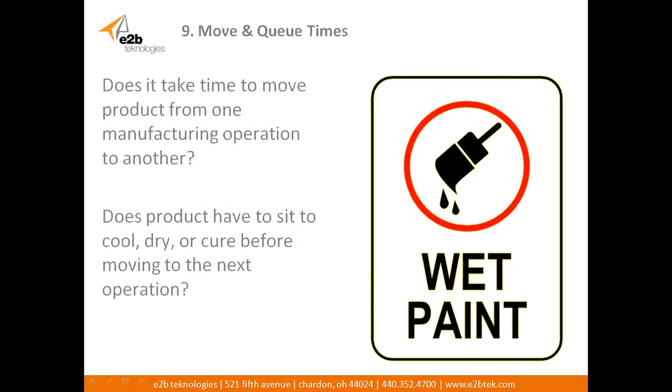Move and queue time. We don't find this in every industry, but it is prevalent in many industries. Move time, pretty self-explanatory. It's the time that it takes me to move my work in process from one machine or work center to another, right? And in many cases, that's in the same facility, so it's not a big deal. But in some cases, I need to actually move that to a subcontractor. Maybe I'm outsourcing heat treating, plating, coating. If I haven't taken into account the amount of time it takes me to move that to my outside processor and then to receive that quantity back in, that's going to dramatically impact, obviously, again, my material plans.